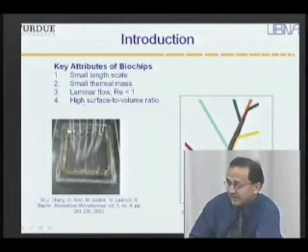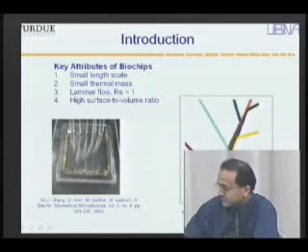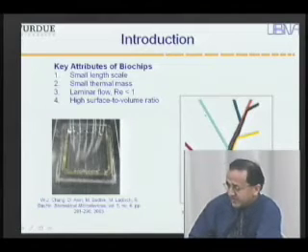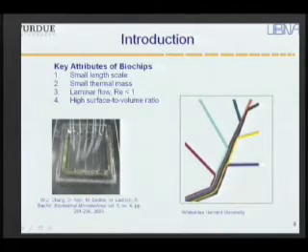What's shown here on the right is this classic picture from Whitesides' group at Harvard, which shows different flow lines. This is a solution with different dye injected into a device, and then you can see that the flow is so laminar that you can actually separate these stream lines into these different outlets, and the flows don't really mix with each other because the flow is very laminar.